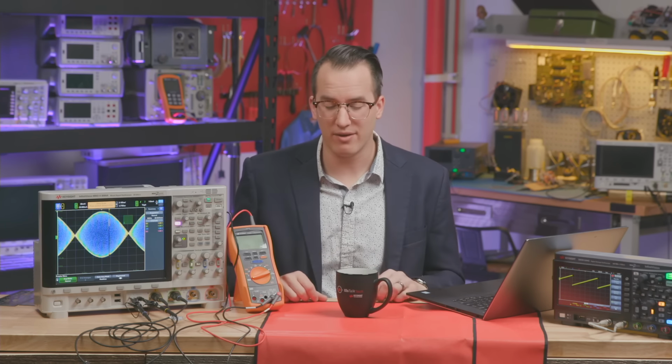Someone asked earlier in chat, right before the stream started, do we have any scopes that run on battery power? We do have an old 6000, not a 6000X, but the generation before this, with a battery powered option. Most people might think they need it, but they don't actually. The times I've seen people want a battery scope is for testing automotive systems out in the field. We really recommend just getting an aftermarket battery pack and running battery that way. It's tricky to get a battery powered scope working the way you want it to all the time, and batteries are notoriously tricky to use. So using an aftermarket pack is what we recommend.